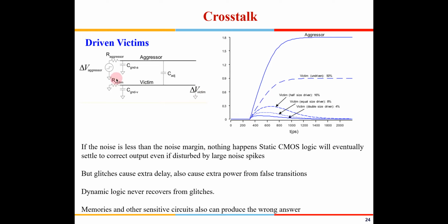It will make a bump and come back, because some charge goes from here to here, although I am transmitting a 0 in this line. How am I transmitting a 0 here? There is an inverter out here, and through the NMOS of that inverter, this line is connected to 0, right? But this line is making a transition from 0 to 1, and because of the capacitance which is coupling these two lines, there will be a bump out here. The output voltage will increase and it will come back to 0, right? Now it says here, if this transistor is very weak, then the bump will be increased and it will remain for a large time. Whereas if the victim size is increased, then the bump will decrease.